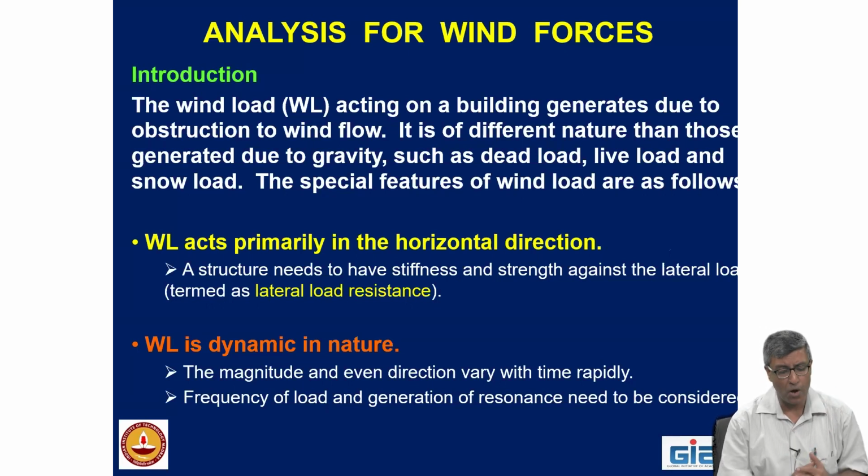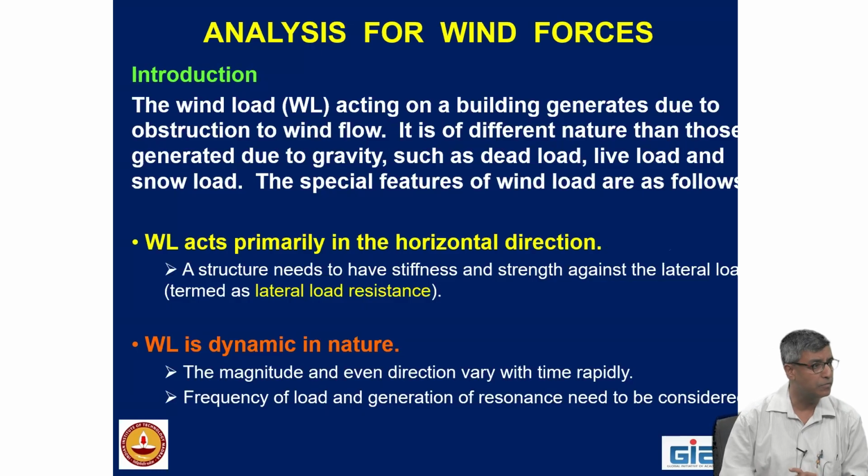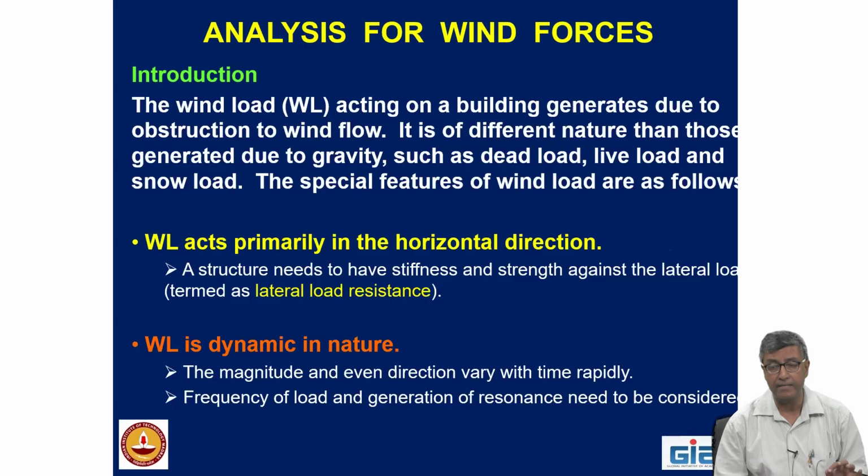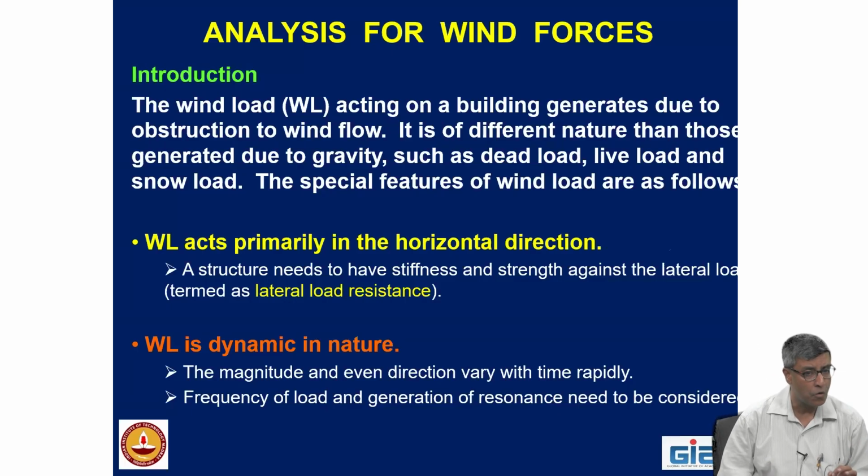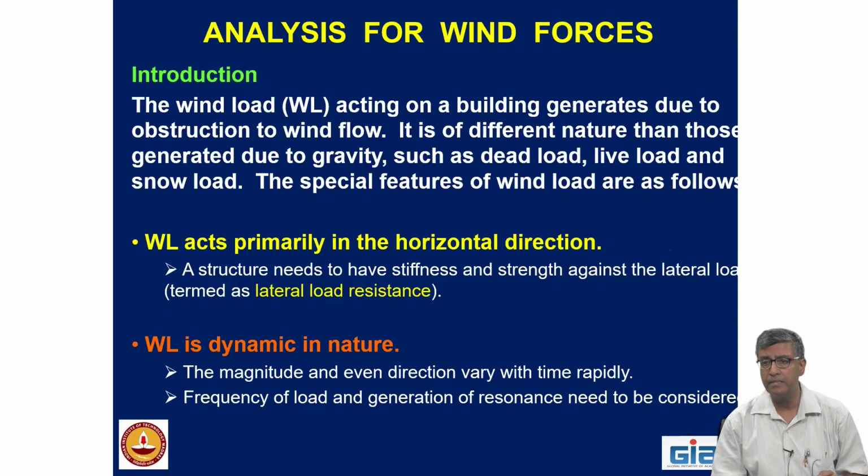Now, it is different from dead load and live load, the gravity loads. See, the gravity loads are there every second, at least the self weight and the superimposed dead load. Wind and earthquake, these are transient effects. They just come once in a while. But then for wind, if I'm talking of precast buildings, the damage can be quite high.